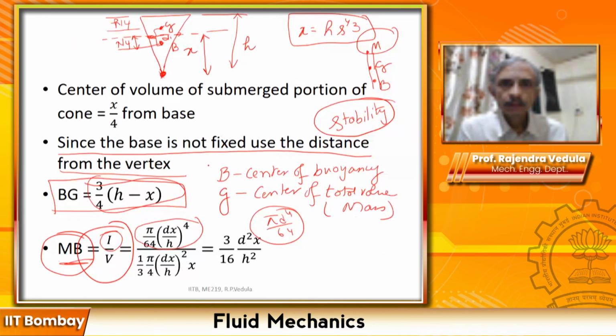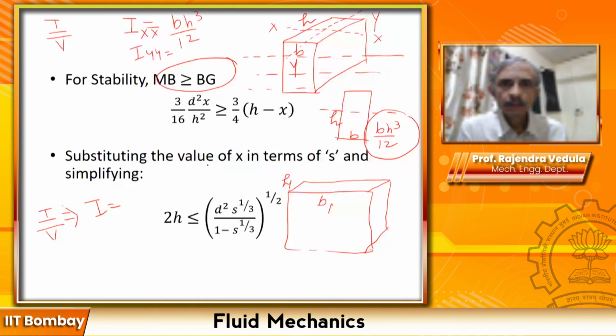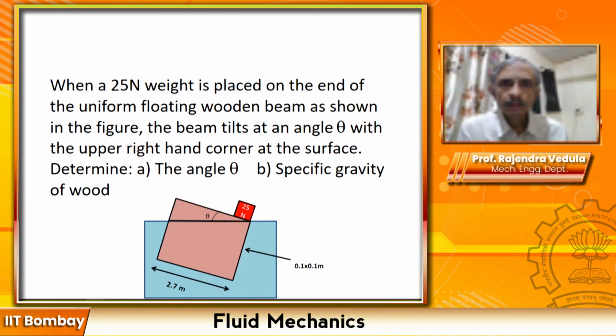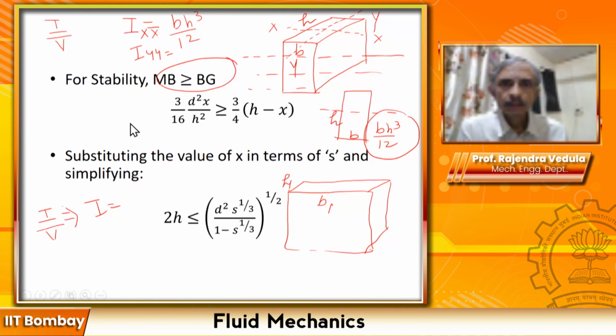I, y, y. Yes. That has to be very clear in your mind. So the I_yy is something that you should be taking and not I_xx. If that is clear, then I think everything is clear. So anybody not clear about what is the axis about which you need to take the area moment in this particular expression? The rest is just brute force algebra.